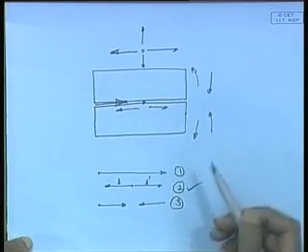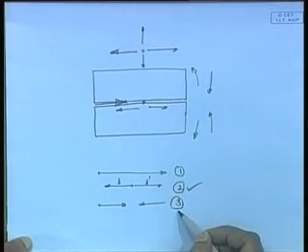Why go outwards? The idea is, as you are welding, the plates are getting more and more rigid, getting stiffer and stiffer, because they are getting welded to some other structure, some panel or butt welding or whatever, so they are no more free to move. So, as I go outward, whatever movement the free edges can take, think of the opposite, it cannot take.